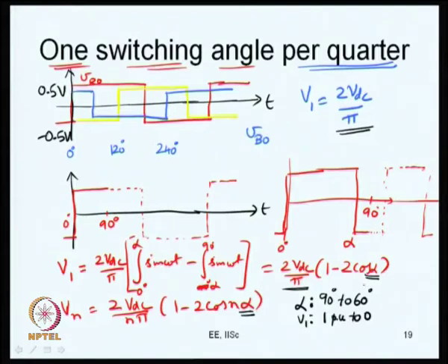For a small variation in alpha, n alpha will have a substantially larger variation. So, what you will see in the fundamental will be a small cycle, but here you will see larger cycles. You will be able to see certain cycles of sinusoidal, cosinusoidal functions coming up here. So, Vn etcetera will change much more drastically than V1 would change. That is what I would like to tell you.